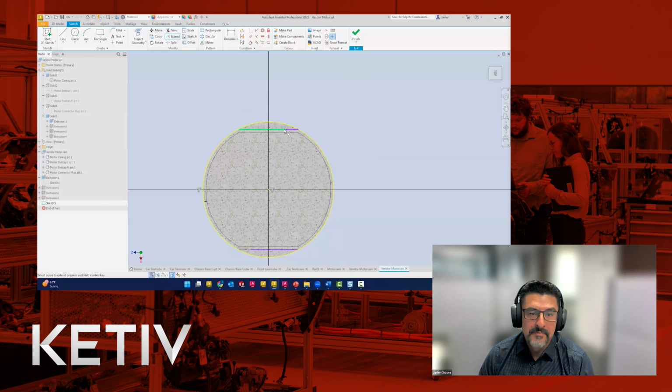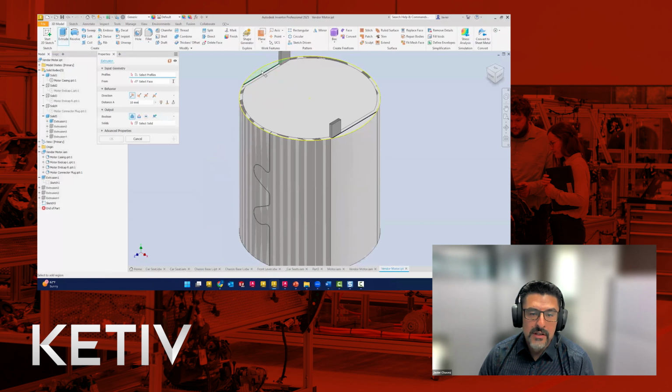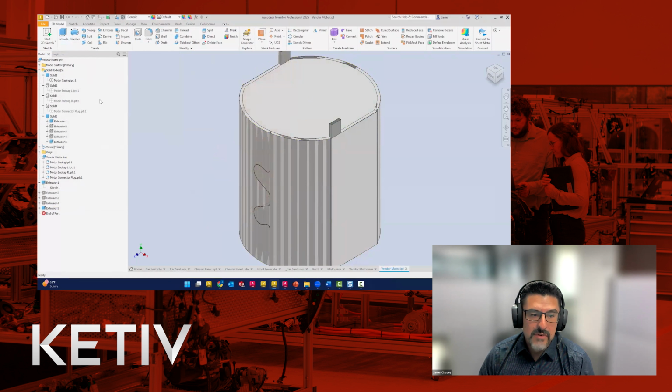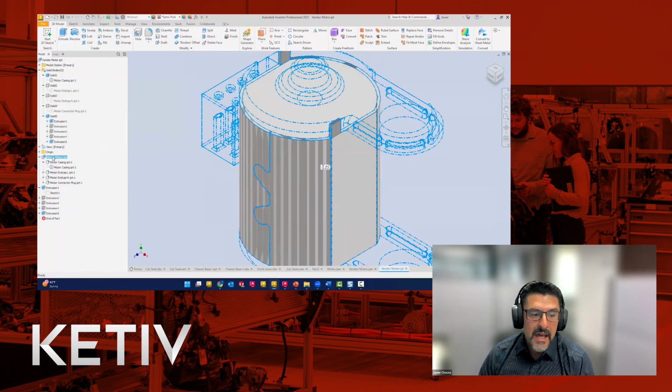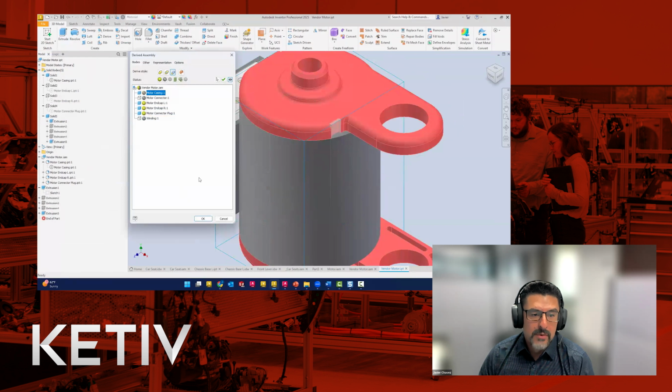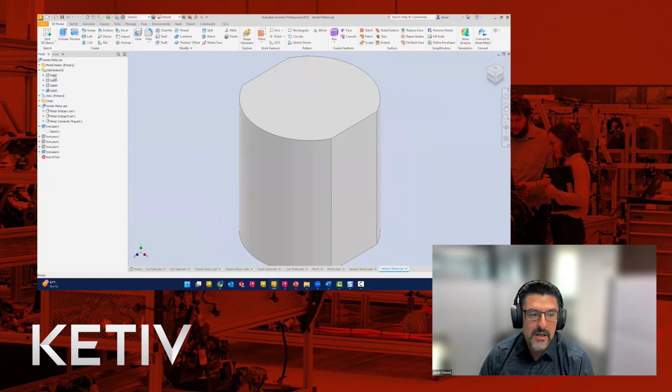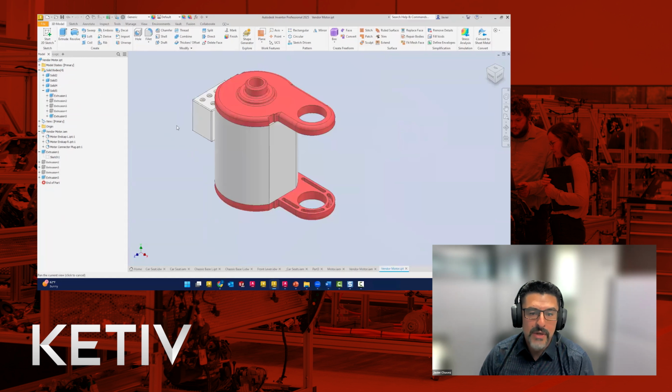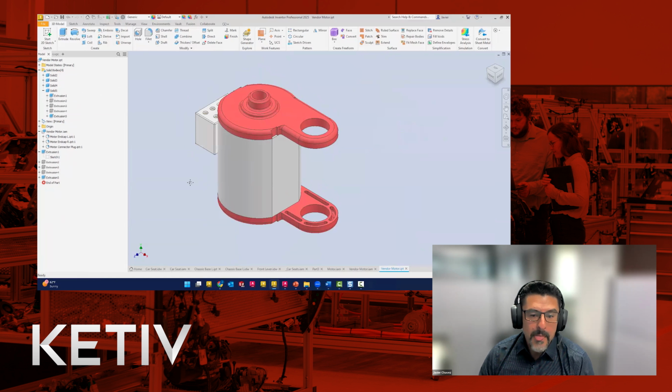So now we're really combining the 3D model with some modeling. But again, it should be less work in terms of measuring, so that we can use common extrusions and cuts to get to what we want. Okay. So we're going to simplify this and create another solid. And once we have a good representation, we can go back and edit our import of this data, and edit the derived assembly. We could turn off the motor casing. It's no longer a part or component of this. It's linked back to the original assembly, but this is now our casing, and ours is better than what we had a minute ago. Okay, so we'll move on to the next part.